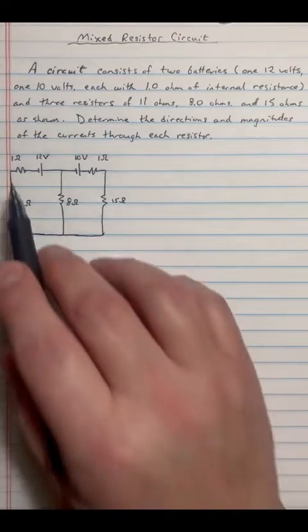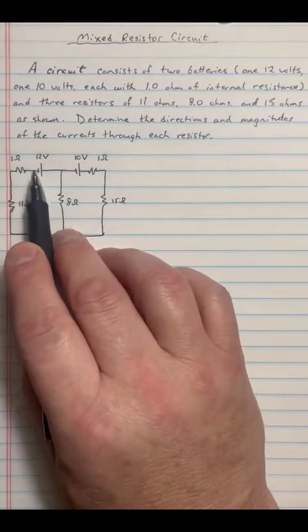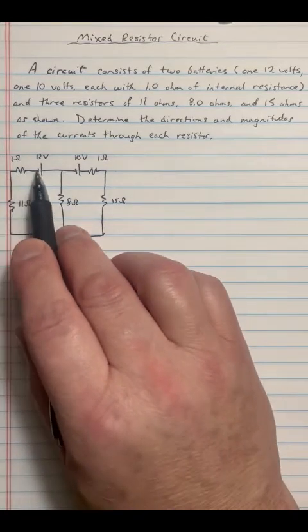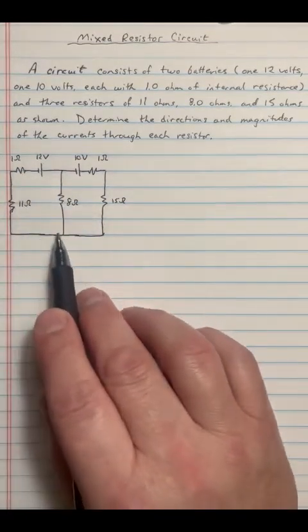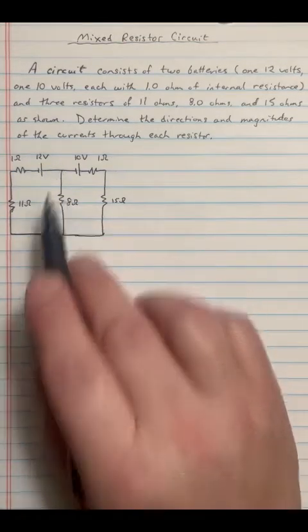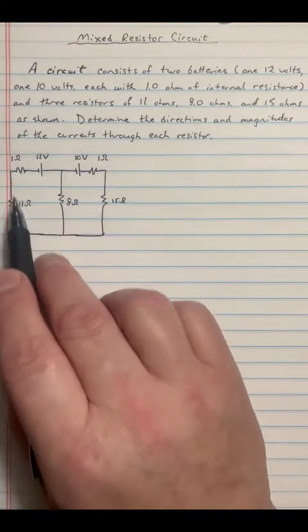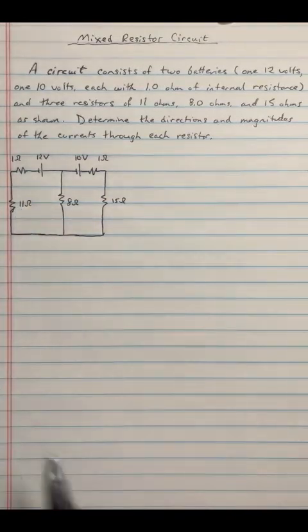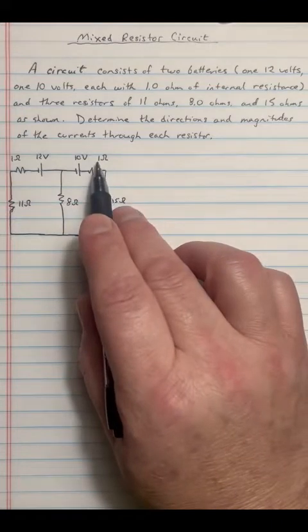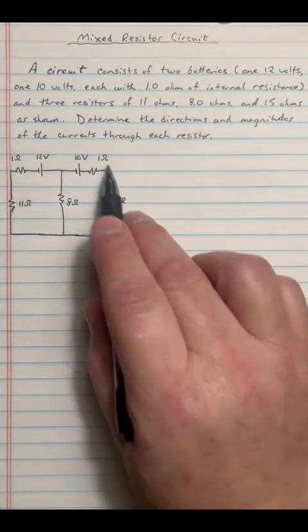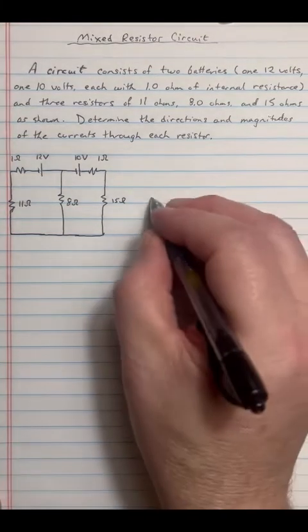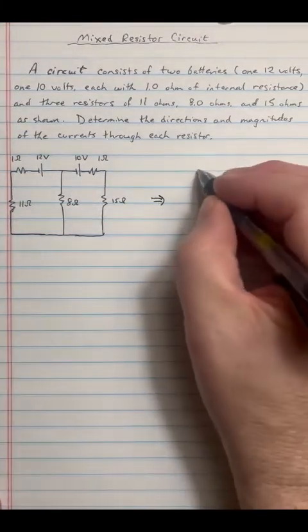And also remember that this resistor here really is part of this battery. So that means that this resistor and this battery, if you look, are along the same wire that starts at this junction, goes along here, and ends at that junction. And because of that, these two resistors are essentially in series. Similarly, now that I've described it, if you look carefully, this internal resistance and this resistor are also therefore in series. And so, for simplification purposes, we can re-sketch the picture.